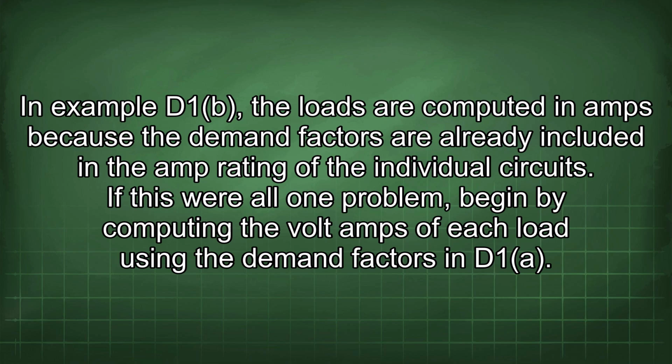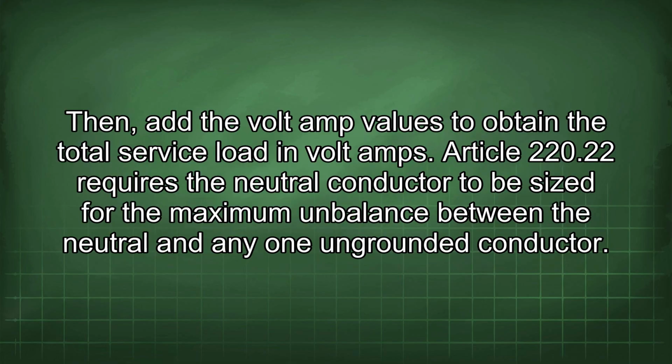If this were all one problem, begin by computing the volt amps of each load using the demand factors in D1a. Then add the volt amp values to obtain the total service load in volt amps.